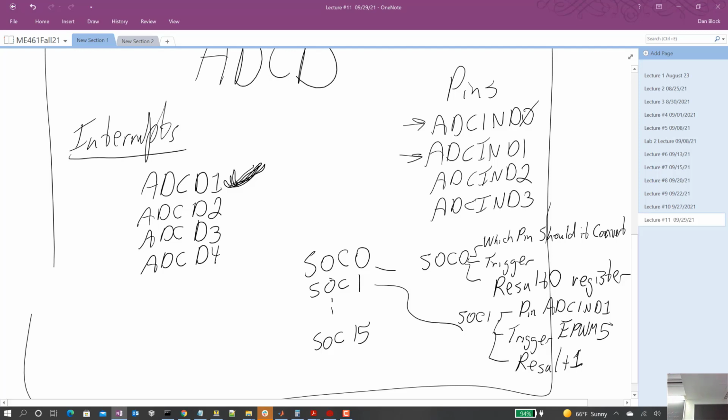Okay. Now, we want a way to trigger our entire sequence, let the sequence go. When the sequence is finished, we want to interrupt the CPU, right? That's our goal for all these exercises when it comes to sampling the ADC. Yes, I'll tell you in the lab we're going to use different sample rates. I think when we get to the microphone, we're going to sample it at first at 4 kilohertz, or something like that, and then we go even faster, play around with different sample rates.